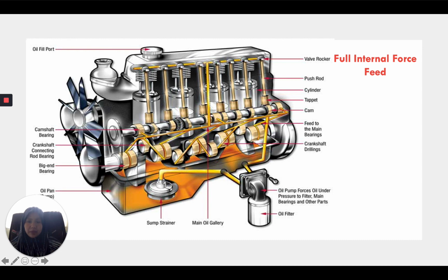As the lubricating oil is supplied to the engine components under pressure, the reach of the oil is enhanced to lubricate remote and farthest points, and this helps in efficient lubrication of engine components and hence in achieving better engine performance. And the yellow in the picture is where the oil from the sump goes to in the crankcase.